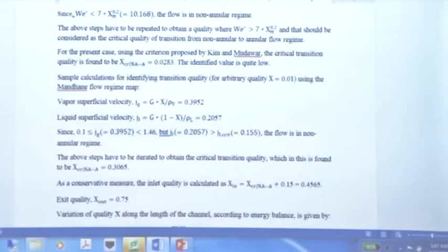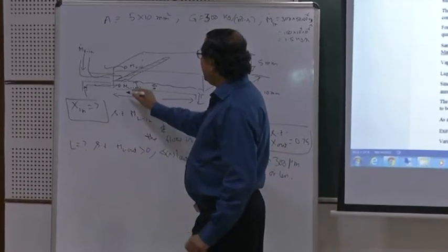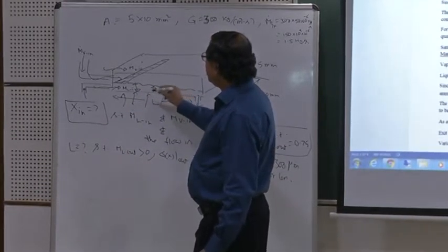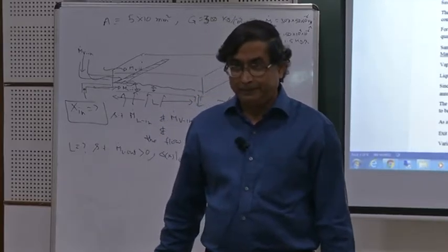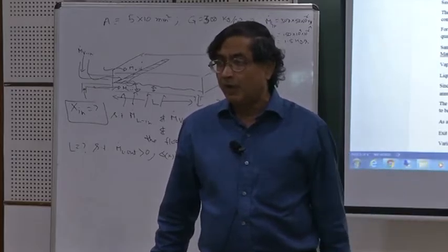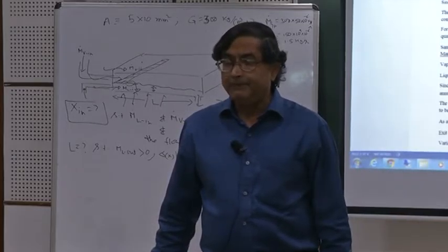Particularly when you come in off the splitter plate, even if you put it all at a uniform heat flux of 50 watt per centimeter square, for a short region after it negotiates the splitter plate, not much heat has come in to evaporate it, because previously it was just warming up the liquid slightly.